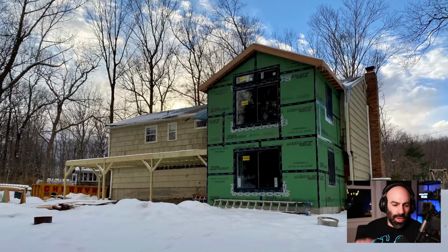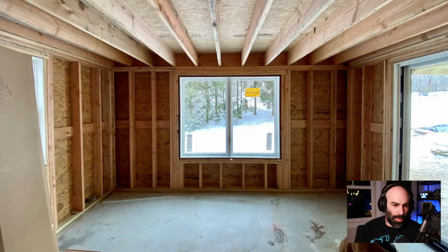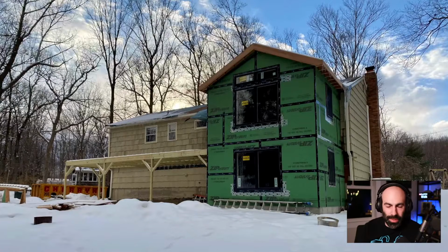So instead of doing plywood or OSB and then a separate layer of house wrap, whatever you want to call it, air vapor barrier, and then taping it, it's basically an OSB type of board with the waterproofing adhered to it, and then you just tape the seams. Some people have differing opinions on it, but I personally like it. So it's basically the sheathing and the vapor barrier all in one, essentially.